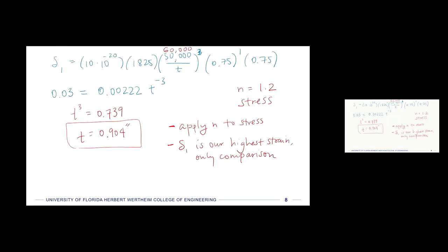So for a thin-walled pressure vessel, you really need the wall thickness to be less than or equal to like 0.1 times the radius or something like that. There are thresholds like that. I think you can look it up in the book as well. And so this does not align with a thin-walled pressure vessel.